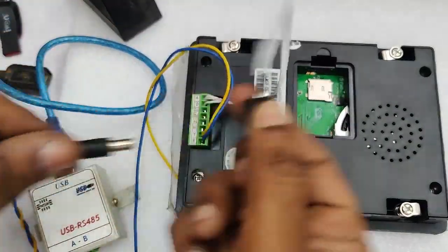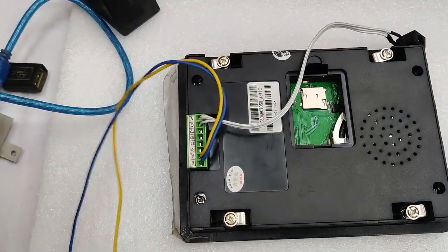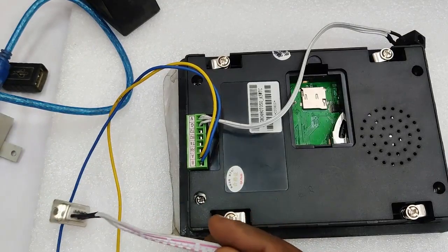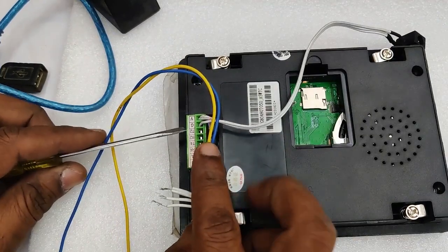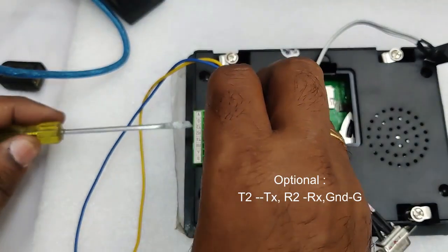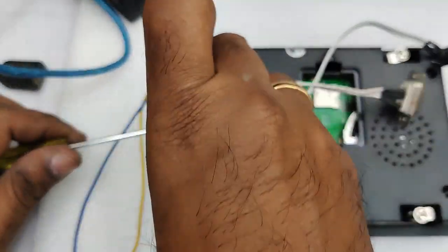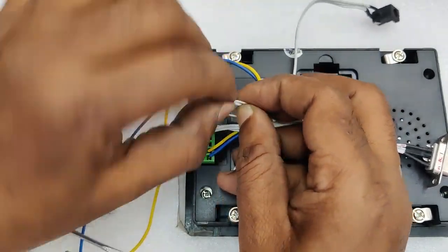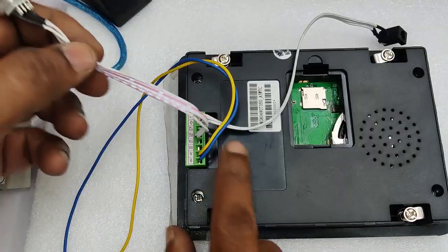This HMI display requires a 12 volt 2 ampere power source, and for downloading the files we generally use the SD card method, and as a supplement I am going to use this UART2 also. As we have to often download the 22.bin file for modification of master, we will be using this method.